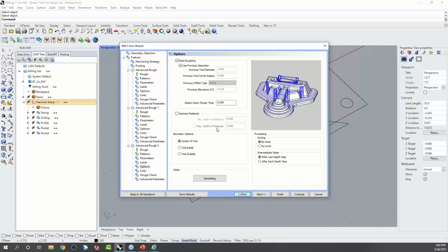And kind of like what I talked about as far as saving a feature, you can go through and set this up one time, be able to save it as a feature, so that way it knows what the stage down is. The other way to do it, this is kind of an automatic method where it does a calculation based on the tool information to find the leftover material, which it does a pretty decent job with.